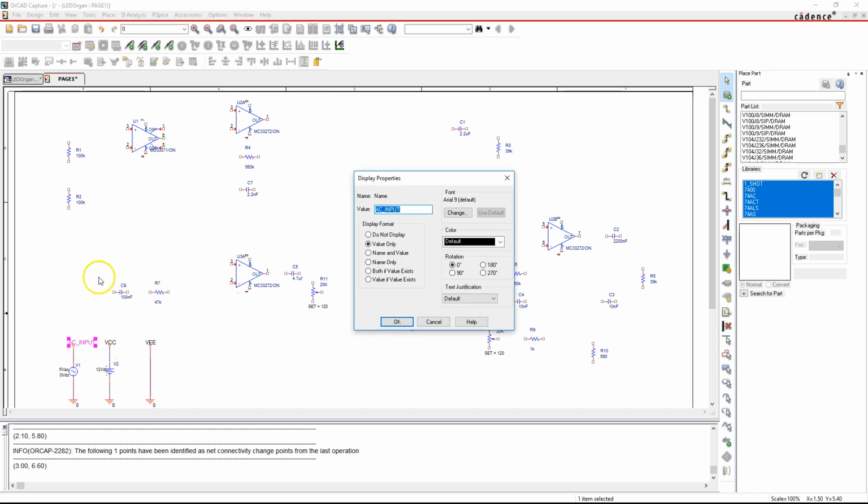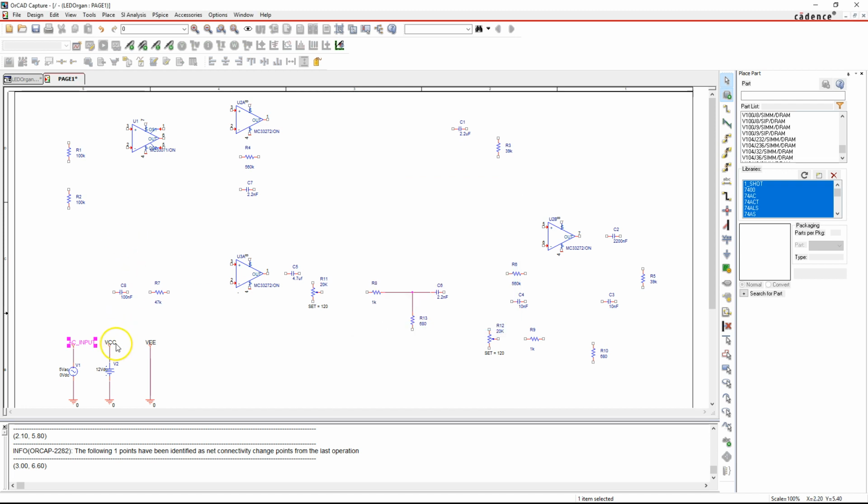This AC input, that is fine. I'm going to copy this VDC bulb here. Now, to make sure that you actually select the part, you want to select here. Move the text out of the way if you have to, and hit Control C on your keyboard to copy it. Control V to paste, and you can paste it any way you feel like, but paste it where something makes sense. So that's at the top of the schematic there. I'm going to bring these components down,